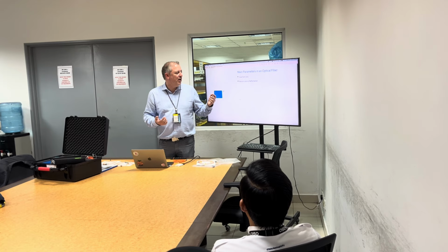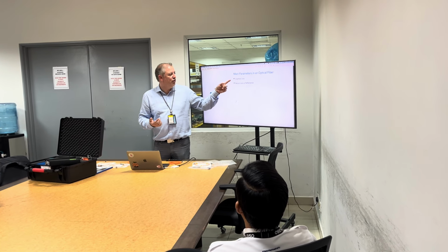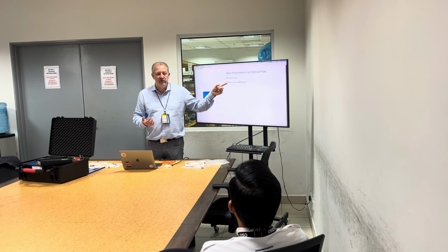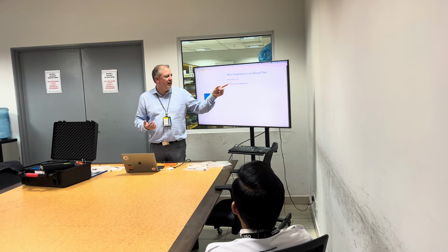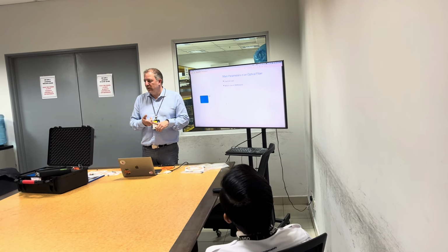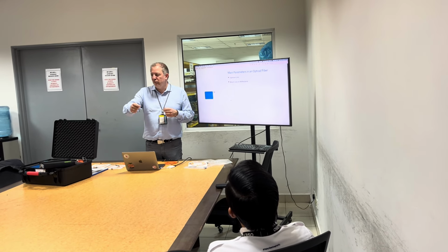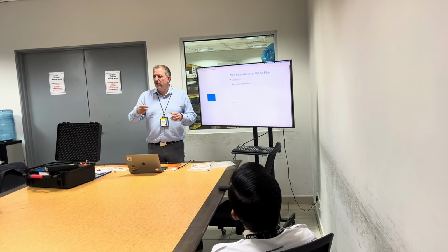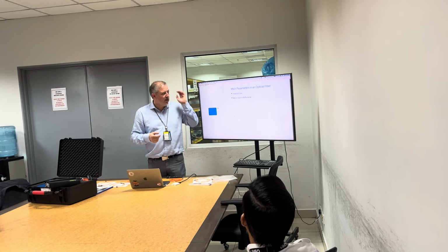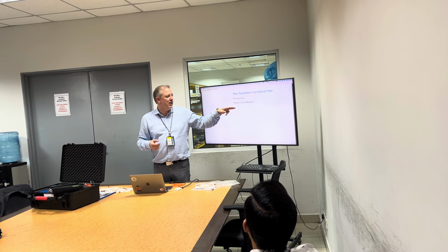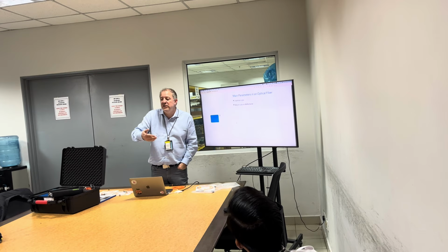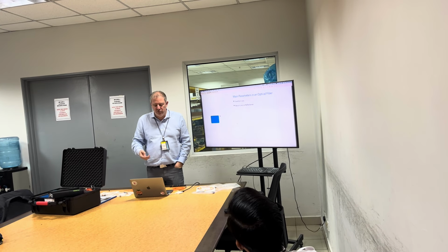So important to notice, our tool does insertion loss measurement. We don't do return loss. Why that? Because insertion loss is going to work either for connector or fault. So that's the light that is going to go through a connector or a fault, and then we'll review that later. Return loss is another dimension that we don't necessarily need to perform when we do troubleshooting.